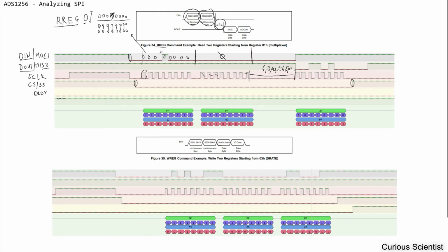It's a bit difficult because with the microcontroller you can only define integer numbers for the delays between the commands to the SPI. So that's one part, and also when you send or receive through the SPI, that also takes time. So you have to sort of experiment with this to get as close as possible to this recommended timing here. So that's all about the timing.